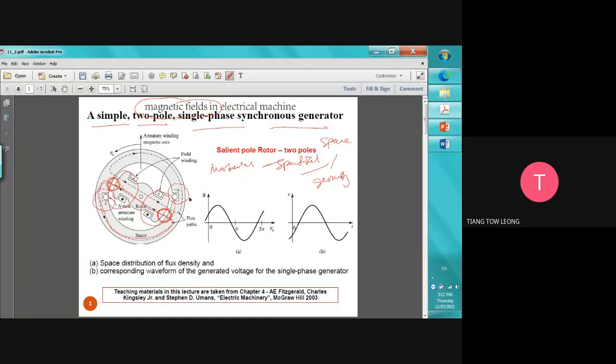So that's why, in the spatial magnetic flux density, we also need to know, for example, B versus theta. Theta starts from zero here, then 90. By default, this is the positive direction. Then 180, then 270, then 360. Maybe from this point, I need to pick it up first. The point where B is this value.